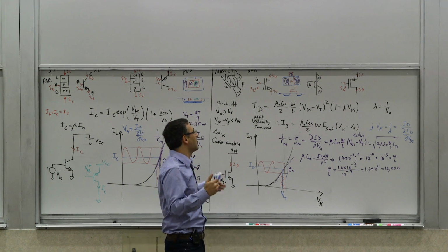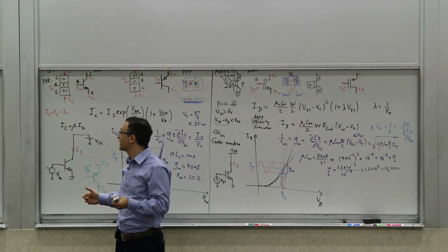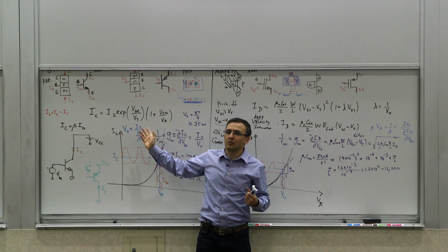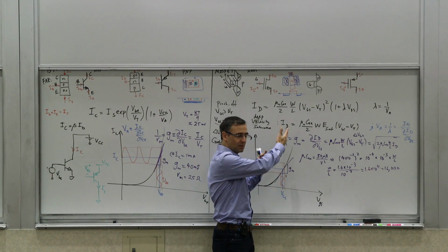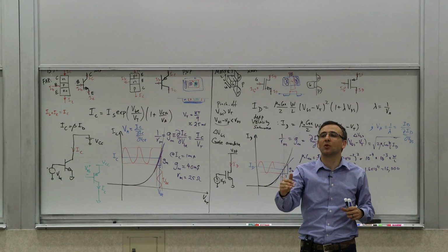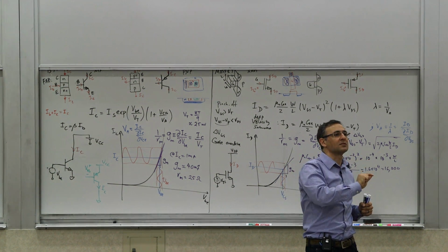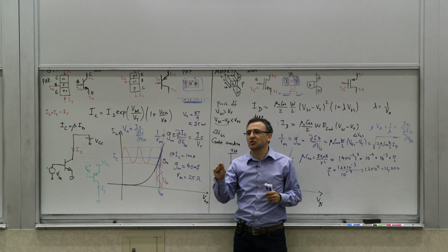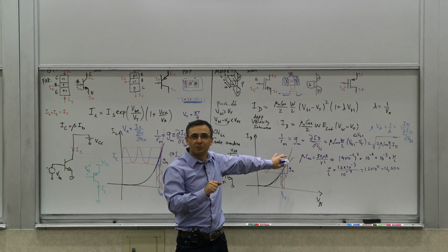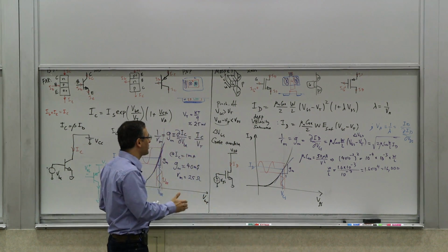You come up with ways of using MOSFETs that people 20 years ago, 10 years ago, did not think were possible. They said, oh, the only way you can do this or X or Y is with bipolars. And then people came up with ways of using these. But this is the basic problem that you're trying to overcome, and it really eventually boils down to impedances. A lot of those solutions boil down to the drive point impedances and controlling that, and coming up with structures that allow you to use the appropriate impedances, probably most of the time lower impedances, without diminishing the fundamental operation of the system. And we'll see examples of this as we go forward.